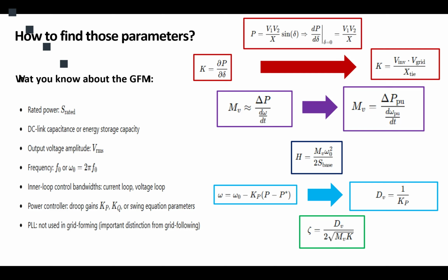When we had a delta P, it would try to adjust the frequency. So there is a certain speed in adjusting to the new frequency. That d omega over dt is the speed of the controller in order to respond to the changes and adjust to the new frequency.